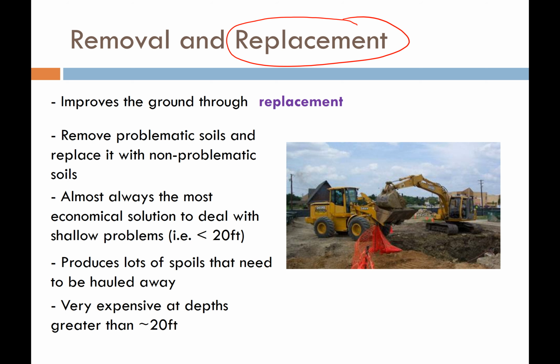Typically, when we excavate out these problematic soils, we're below the water table, and so if you just dump soil down there, oftentimes what happens is the sand just settles in the water, and it settles in a very loose manner, and you can actually make the problem worse.